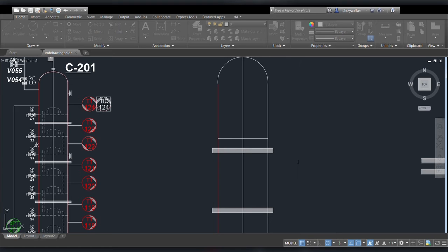and don't forget to change your global scale factor to at least 30, so that you'll be able to notice the gap between each dash. Because if we were to use a global scale factor of 1, then we won't be able to notice the dash at all. We can barely see it. So let's try to do that, right?